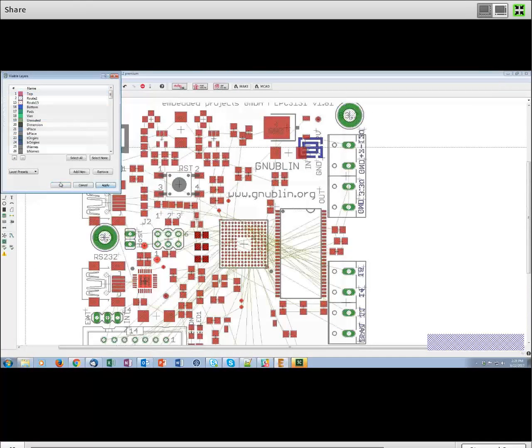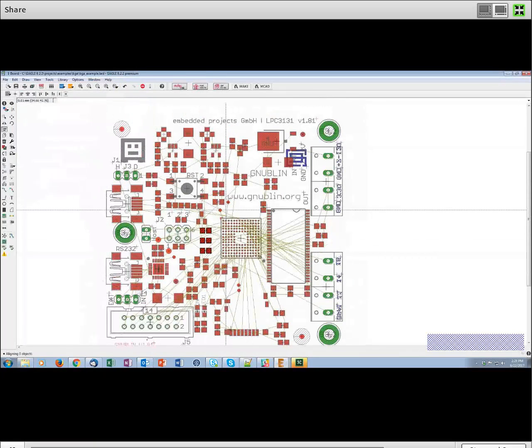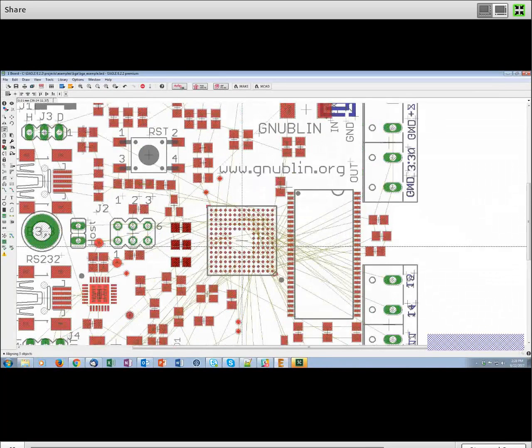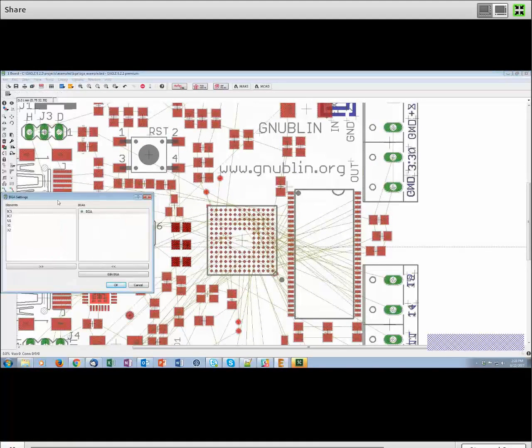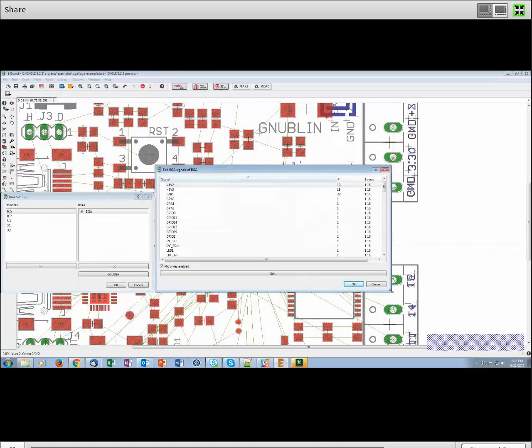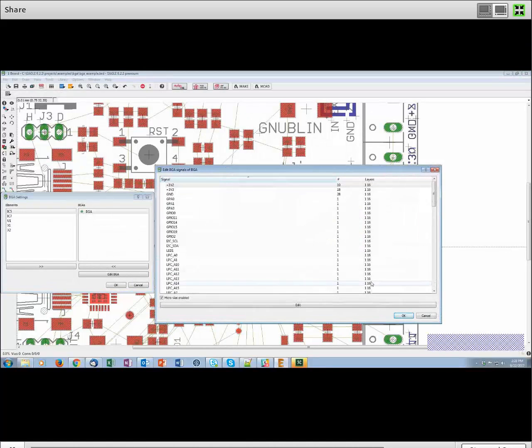So in order to use the BGA fan out tool, there has to be a BGA component in your design like we have in this example that ships with Eagle. So what we do is we click on the BGA auto router. It looks at the various ICs that are in your design. We've already selected the BGA component to be the one that we're interested in fanning out. If we click Edit BGA, we'll open up this screen, and there's a lot to see in this screen. You have your signals. You can dictate what layers they go through.